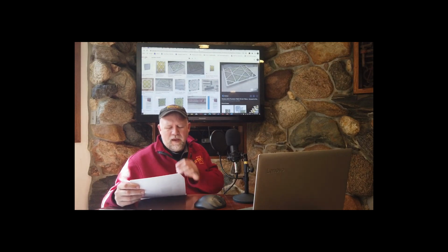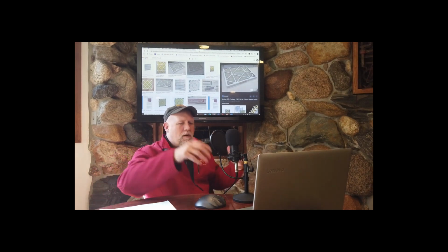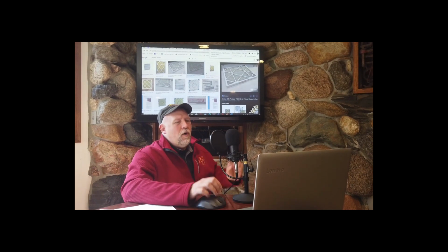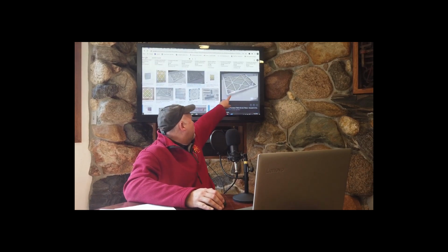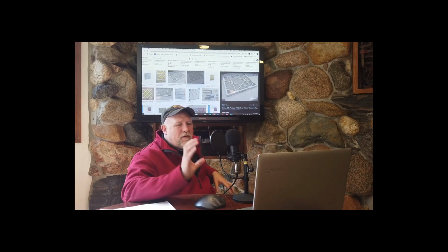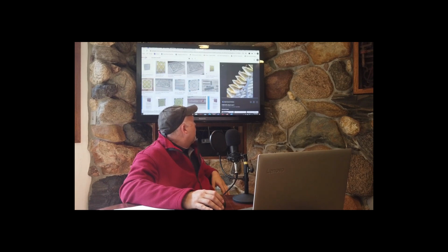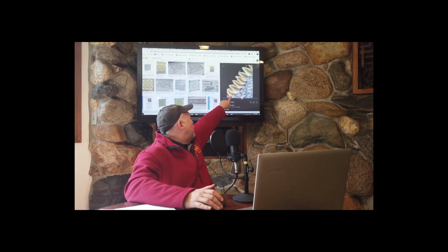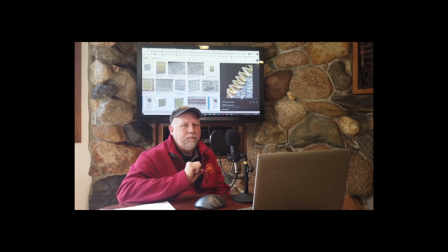This has a MERV value of 8. Remember when I said this is like what I would consider the starting point for commercial filters? Notice this one is pleated. Here, check out the picture. You'll see within the filter itself, the face of the filter, it is pleated. Here's a cutaway version. Notice it's pleated, and it also has wire on it. That wire helps it hold its shape.